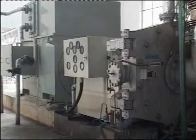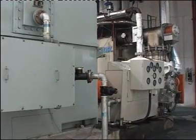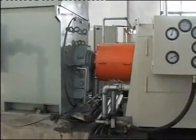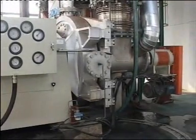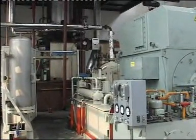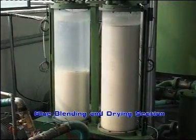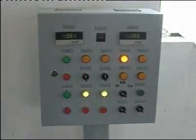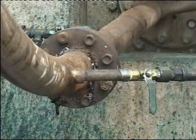A 48-inch refiner imported from Europe is selected to meet the fiber capacity and quality requirements of 80,000 cubic meters per year MDF production line. The glue spraying device is arranged at discharging valve, and the paraffin injector is set in the front of grinding chamber.